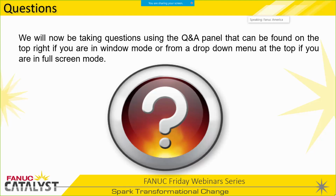I'm not sure if that's released yet on R30iB Plus. I think it is, but in that case, you put the grid down, you move it to the robot. It uses a robot-mounted USB camera to find the grid and actually do the track frame and the camera calibration all in one. That's auto grid frame set, and I would talk to your salesperson to find out more about that, or send an email to visual tracking at FANUC America. Someone can get back to you with that.